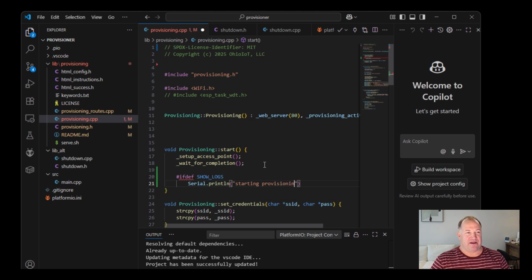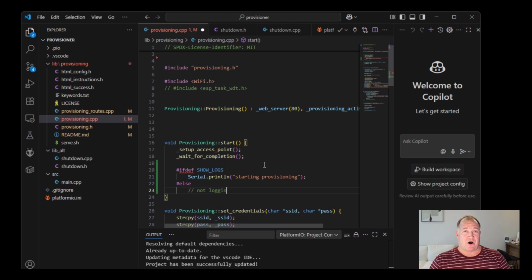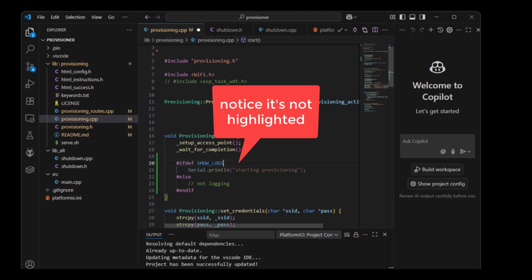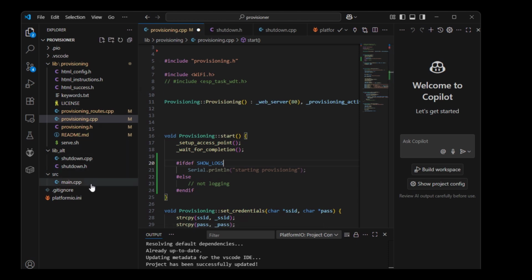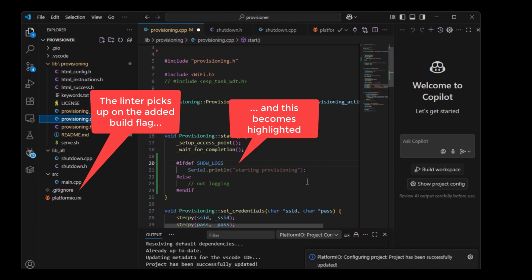Complicated is having 4 separate pieces of firmware for 4 different temperature sensors when all 4 do the exact same thing. By using build flags, you can make the same piece of code do different things based on the flags that are present in your PlatformIO.ini. This reduces the version control burden significantly. You can have one piece of code doing 12 different things, and you can trust that it's going to work because you don't actually have to change the code once you already know it works.